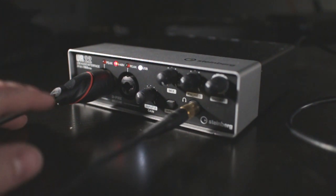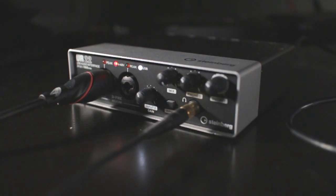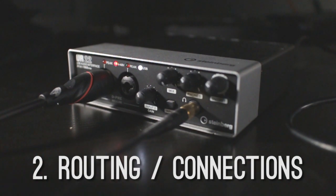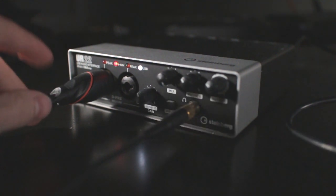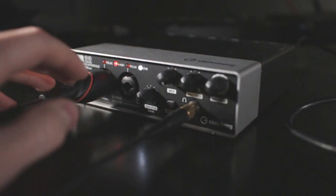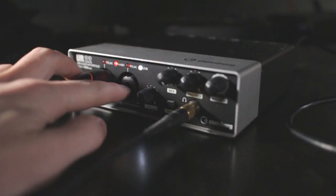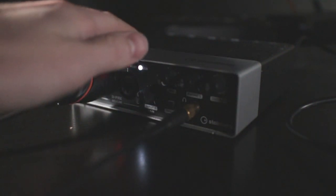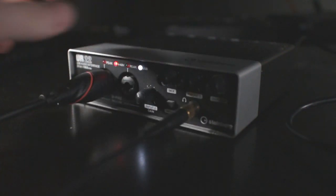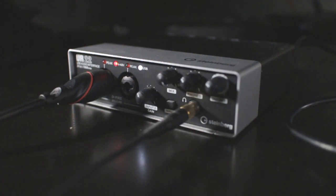So first of all, these take care of those conversions, and they also open up a whole new world of routing options. By routing options, I'm actually talking about the physical connections that you're able to use. So whereas on your laptop, you might just have a 1/8 inch aux port, on this external interface, for example, I have two XLR/1/4 inch combo inputs, I have a headphone output, and on the back, I have two 1/4 inch outputs for my studio monitors, as well as MIDI in and out. So lots more routing options, and ones that are a lot more industry standard as compared to the connections on your laptop or your computer.